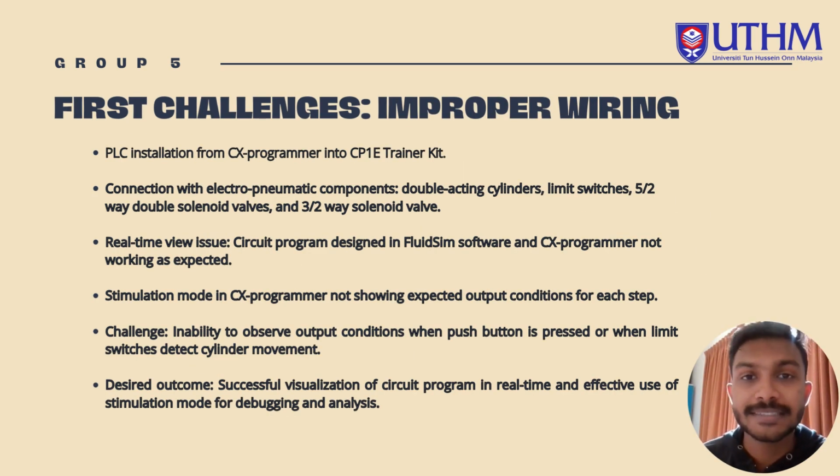All right. So the first challenge is improper wiring. PLC installation from CX Programmer into the CP1E trainer kit. Normally we design in FluidSim software and also the CX Programmer software. After that, we install them into the CP1E trainer kit, where we have to assemble all the components we used. The components we use are double acting cylinders, limit switches, five two-way double solenoid valves, and three two-way solenoid valves. So as a real-time issue,